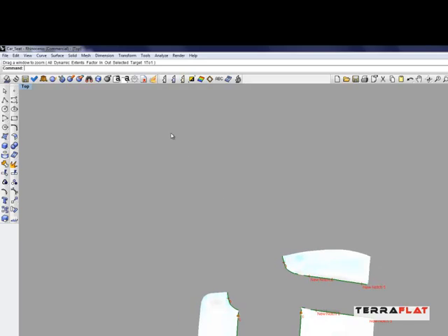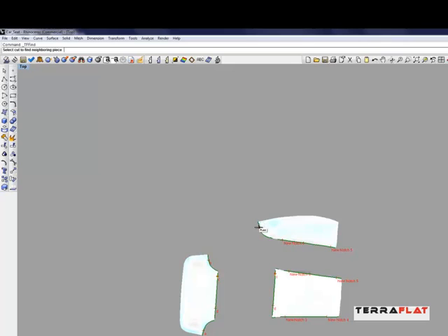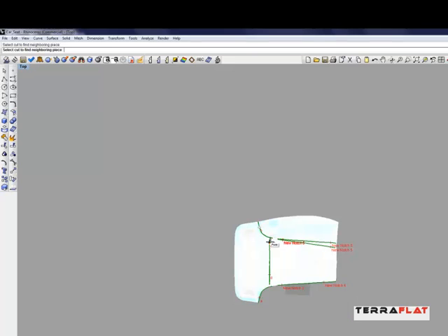Now I may want to go back and use the Find tool again, and if I just click on the notch, it'll put these pieces back where they would go. So we have our piece now ready to export. We've added our seam allowance of 1/2 inch, and we've also added our notching information. So when they go back to sew these pieces together, we have notches that will allow the sewer to see exactly where all the pieces should go back together.